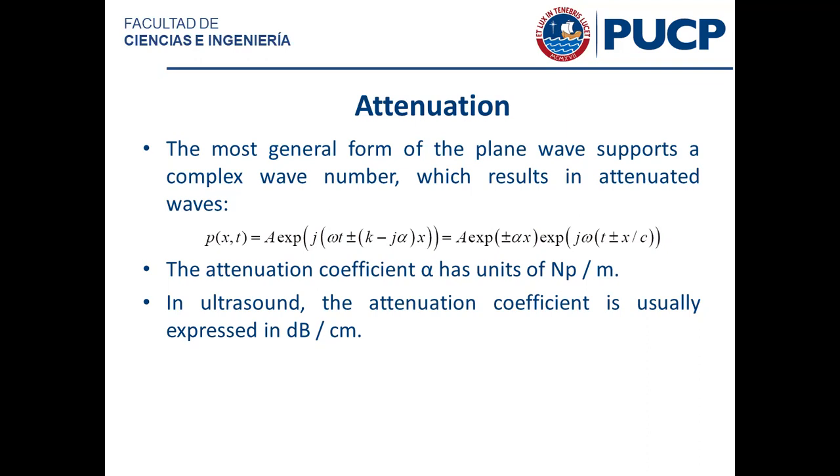So it would be 0.5 times 2, that would be 1 decibel per megahertz, which means that at 1 megahertz, the ultrasonic wave is going to be attenuated by 1 decibel, which is nothing. But at 10 megahertz, the signal would be attenuated by 10 decibels, which is an order of magnitude. In general, that's what happens with ultrasonic waves. The higher you go in frequency, the higher the losses due to attenuation when you propagate deeper into the tissue.